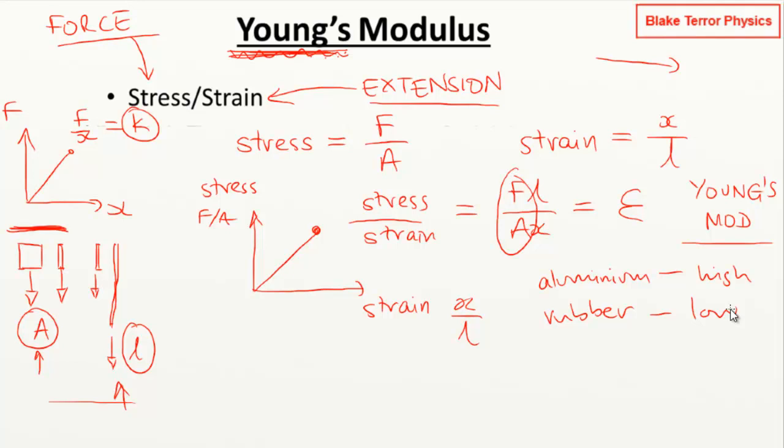Now, with Young's modulus, you can't just say this is how a material behaves in all directions, because a lot of materials have got some kind of grain to them. You think of carbon fibers and things like that. Anything which is fibrous in that way, you've got the difference between applying a force along the grain or across the grain. So depending on which direction an object is loaded in, you might get a different Young's modulus. So it's not just the case of, here's a material, here's Young's modulus, off you go. It doesn't change. That's not the case.